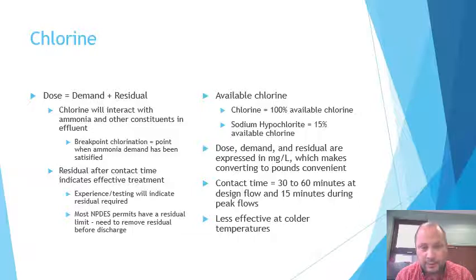But basically, chlorine is very reactive and it'll react with a lot of different constituents in the wastewater stream. Ammonia, ferrous ions, if you use ferric or ferrous chloride for phosphorus removal, nitrites and nitrates, if you have those in your flow after nitrification to remove ammonia.